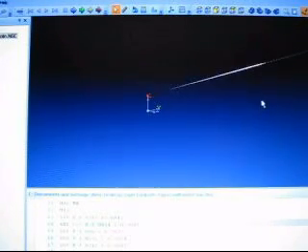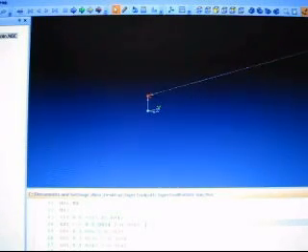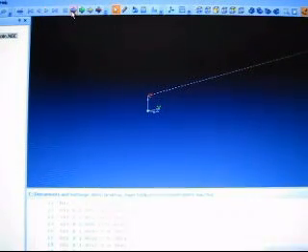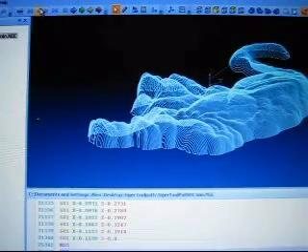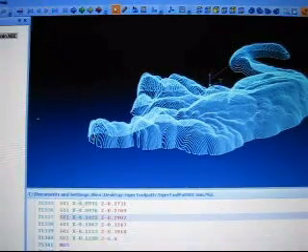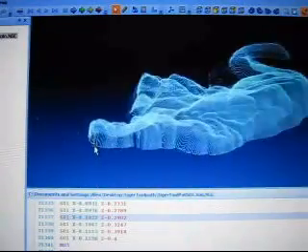And I can give that an F20 command for feed rate 20, and after that I want this thing to feed at 60, so I'm going to go F60. There we have it. Now it's going to feed from that point on and start the toolpath. So this is just going to be my normal feed rate. That's it.